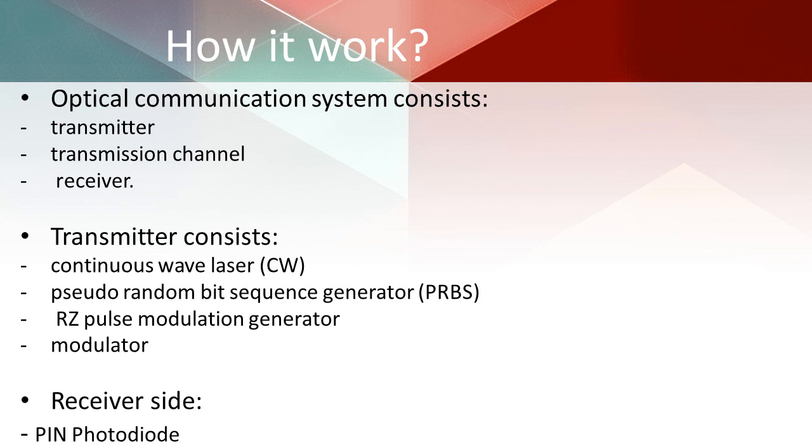The continuous laser has a 780 nanometer wavelength at 100 milliwatt power, and is modulated with different modulation formats in the amplitude modulator, optical and electrical. A modulation index of 0.5 has been applied to the amplitude modulator MZ.